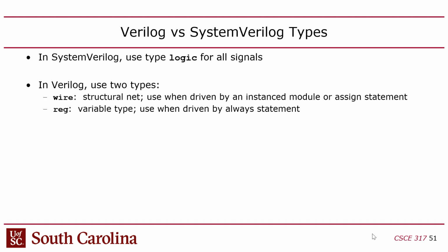which is absurd because a lot of times, when you're setting up your module and declaring your signals, you don't know what it's going to be driven by. You may change your mind, right? And inevitably you'll get an error if that happens. So it's not a big deal, but you're constantly having to change the declarations of these signals. Obviously people recognized that this was ridiculous, so they fixed it in SystemVerilog. But if you write in original Verilog, you still have to deal with that.